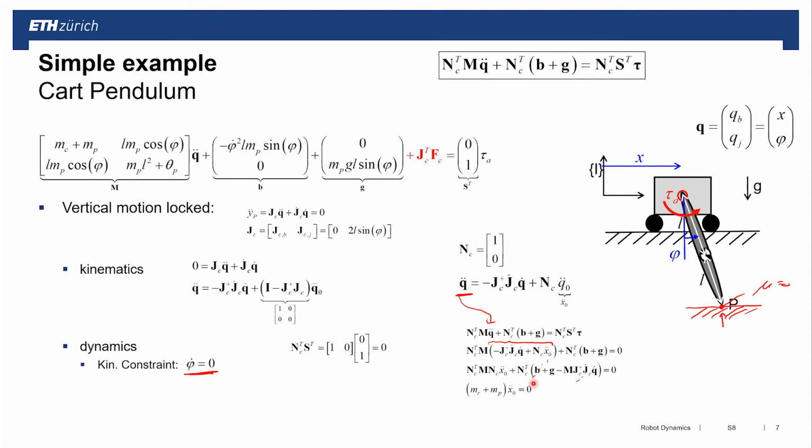So what does that mean? If I'm blocking this system on the ground, all I can do is move it in this subspace in horizontal direction. So the x double dot times the mass here must be the external force in this direction. But we don't have an actuator right now. The only actuator is in this degree of freedom. So in other words, this is a free moving setup. One degree of freedom, total mass is given, the acceleration is what we have to identify depending on the initial conditions.